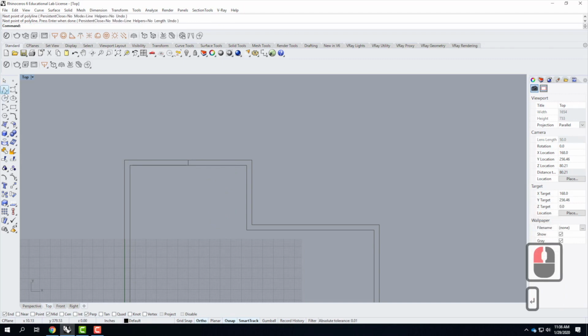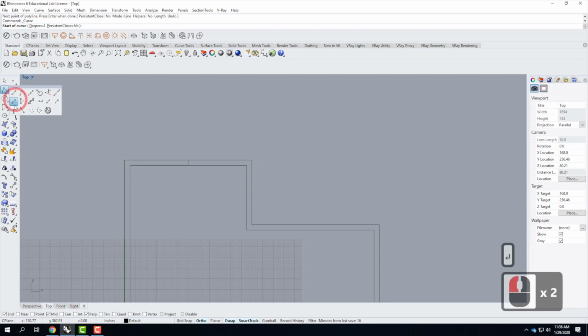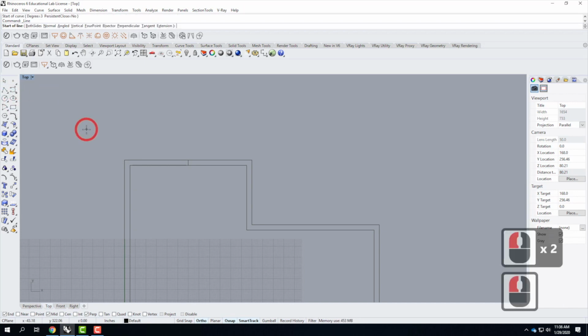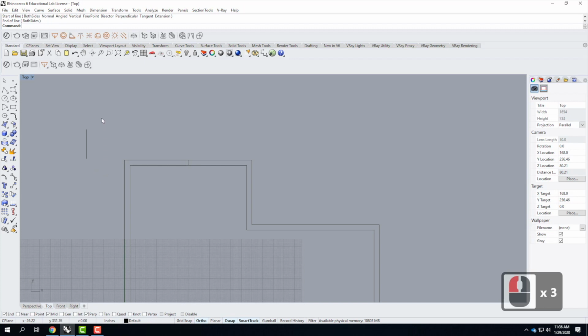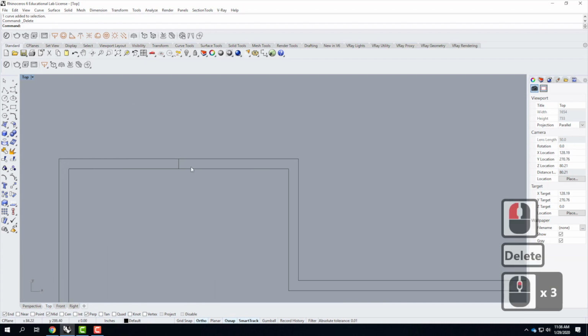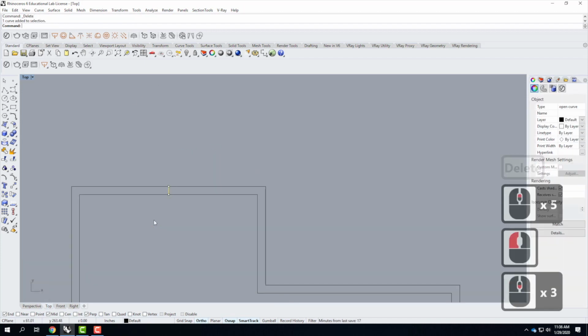If I were using just the line tool, which is right here, it would end after the line is over. So it's one extra enter using the Polyline tool instead of the line tool. I'm so used to it that I don't even think about it. So there's my line. It's in the middle. I need now to establish the opening for this door.